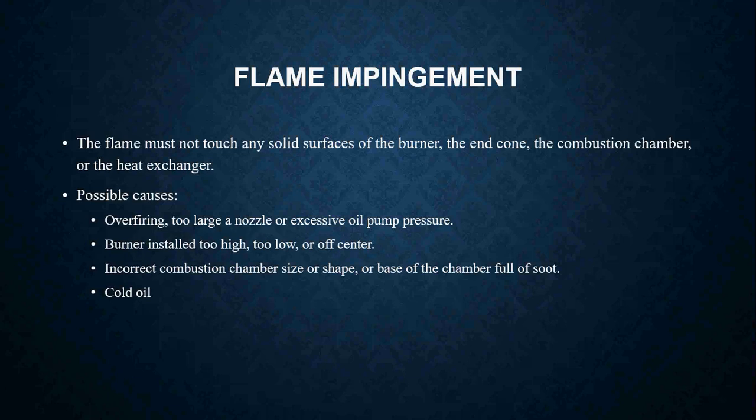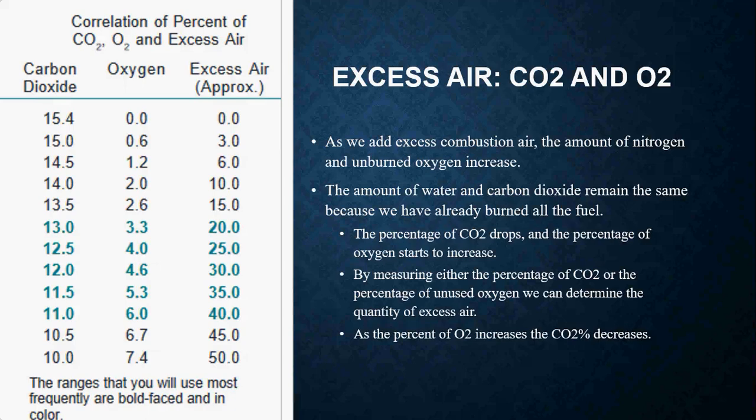Incorrect combustion chamber size or shape, or the base of the chamber is full of soot, or obviously if you have cold oil. That's a big problem if you have outdoor tanks, especially in the dead of winter because of those viscosity issues. The oil droplets are going to be bigger, and therefore it's not going to burn completely. The flame may be a little bit bigger. When it does light off, it's going to impinge on something.